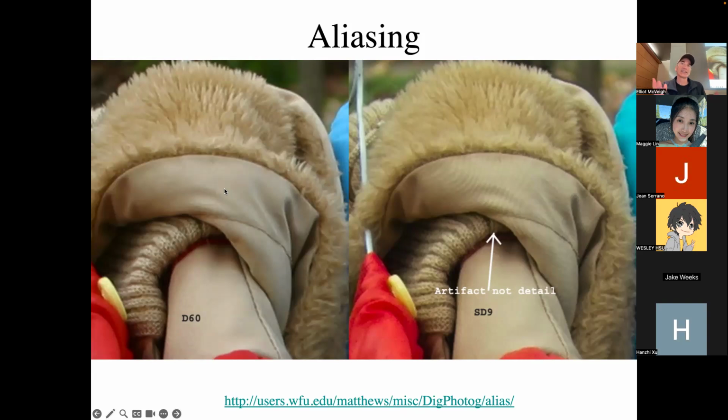So there is an underlying frequency component to the texture of the material, to the weave. If you look at the weave of the material, it has a specific fundamental frequency. And there's an interference between the sampling frequency on your detector in the camera and the actual underlying frequency, and it shows up as this low frequency modulation, because the camera can't detect it. It's too high, yeah.